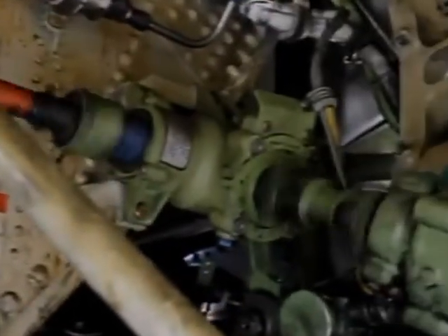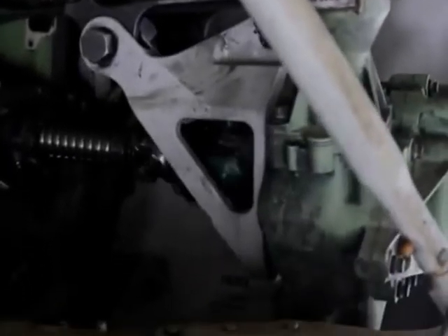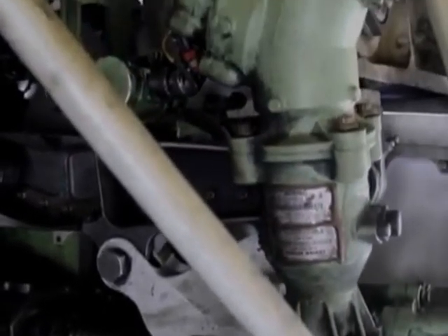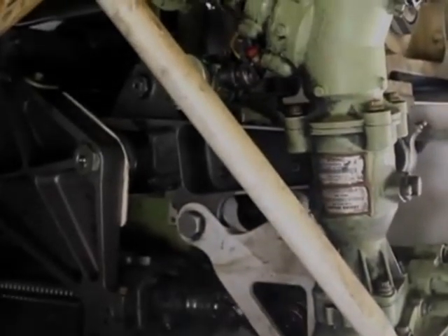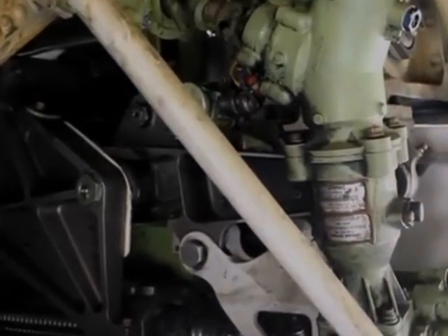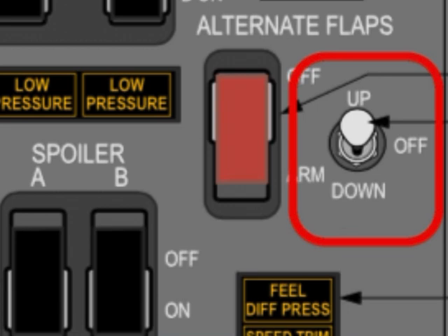Then we have another problem associated with the trailing edge flaps, which is the split flap. Split flap here means that, for example, the lever is moved from any degree to a higher degree, but the flaps are totally not moving on both sides, left and right. There is no asymmetry, but they are totally stuck and not moving down. Mainly this problem comes into effect if there is damage or some problem in the drive mechanism. So based on the non-normal checklist, we try to extend the flaps by the alternate method, by electric motor. This is one way to get rid of this problem.